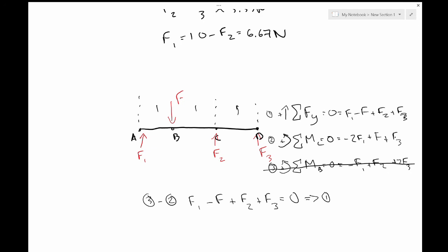A lot of the ways that we get around that on the team is by making worst case assumptions. So if this load F is going to be distributed as F1, F2, F3, and we can't determine what F1, F2, F3 are, we might make the worst case decision. Let's say that F1 equals F2 equals F3 equals F, which is obviously not realistic. But if having each of these forces be big is bad, then by overestimating them, we know that we're going to be on the safe side when we're designing components.